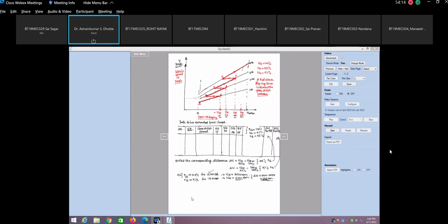So if you drive the vehicle with half clutch or partial clutch engagement, there are two losses. One is the vehicle will not give good fuel efficiency. The second is you are creating relative motion between the clutch plates, and if there is relative motion, there are chances of more heat generation in the clutch. At times the clutch may burn. Such things happen. Then clutch failure happens because of such driving habits, and moreover we are polluting the environment.